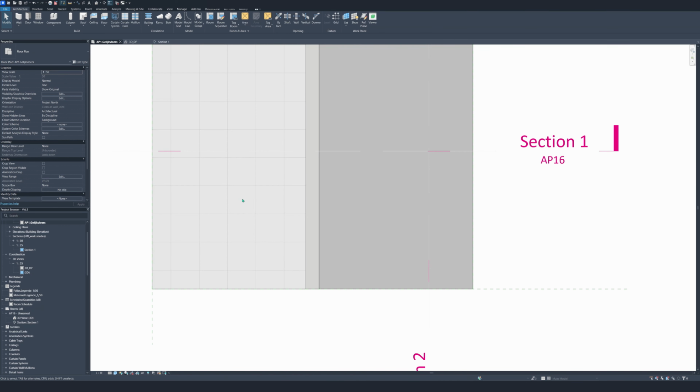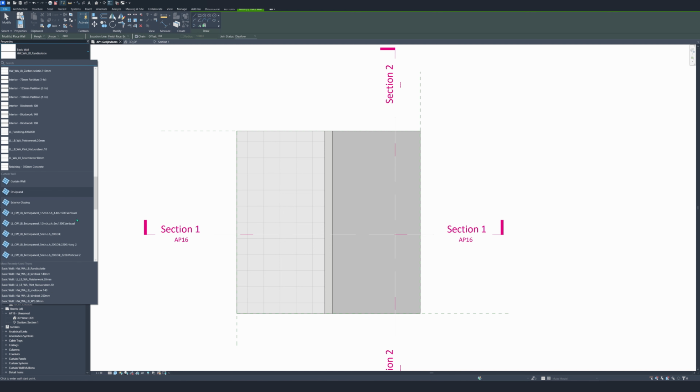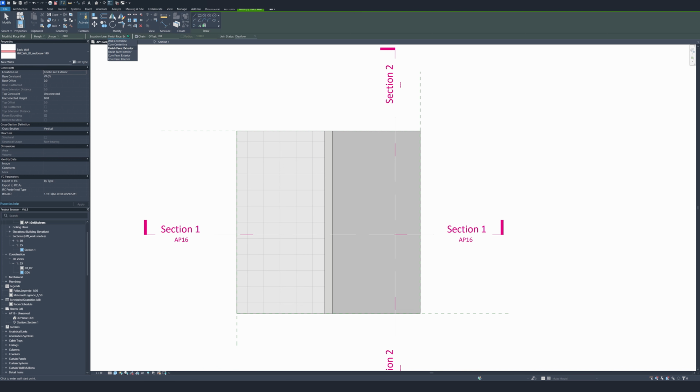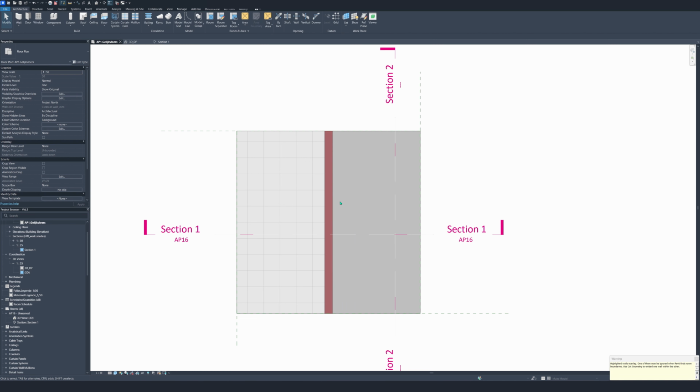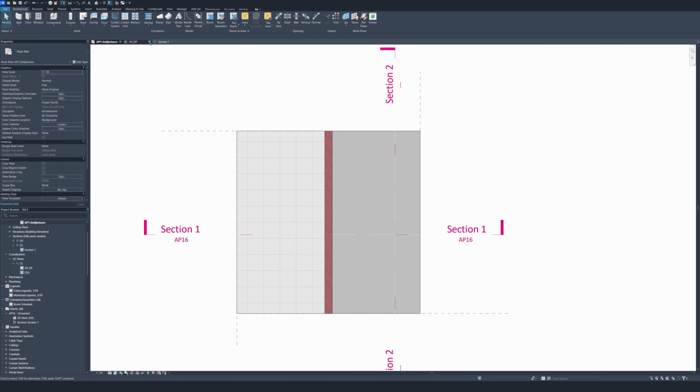So again, to the ground floor, WA, selecting the wall right here. Finish phase, we're gonna change it to core center line, disallow join, and there we go. Now we get the thing here that the walls are overlapping, but that's okay. We're gonna change that. We're gonna make the connect height this one, right? And now we're gonna change.